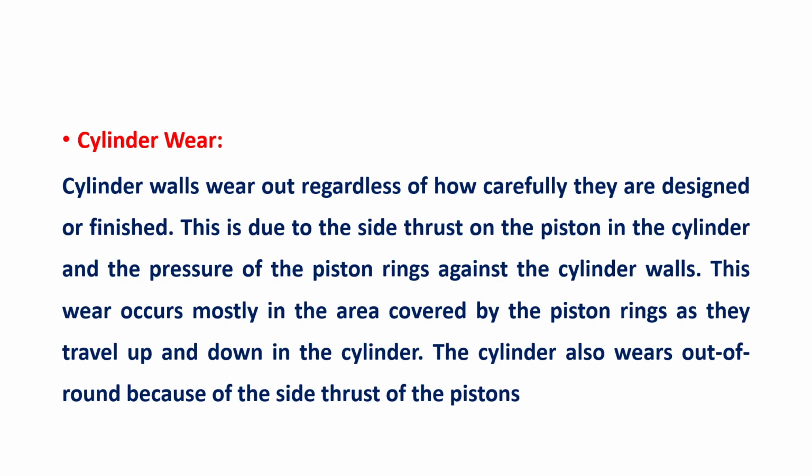The cylinder wears to a taper, and also there is an angular relationship between the connecting rod and the crankshaft. Due to this, the pressure exerted on the piston is much higher during the power stroke. As a consequence, cylinder wear will be more on the power thrust side, and it will begin to go out of round. It will not be a perfect round, and you will get a taper.